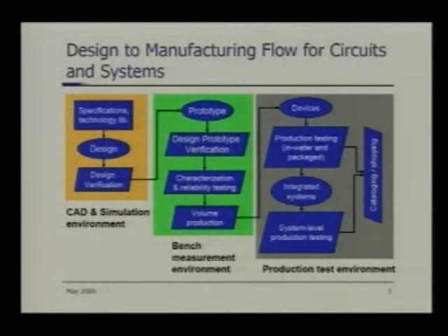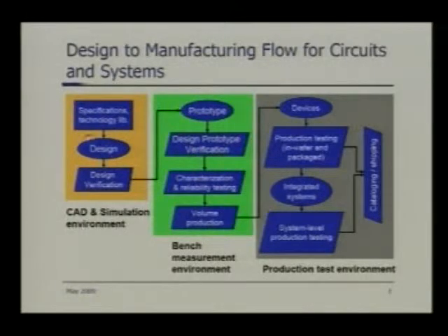We have to automate. So in case of production testing, there are two levels of production testing. One is the wafer level production testing, and second is the package device production testing. So when you fabricate your IC, they come in wafer. So basically each wafer will be containing thousands of devices depending on the die size, and you use the so-called equipment wafer prober to touch down on the wafers, particular devices, to excite the device with particular test stimulus. You observe the test response, you calculate the specification, make sure the specification is meeting the specification you started with.